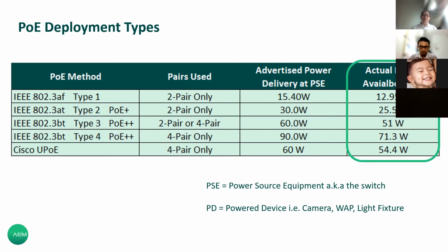So as you can see, we have various voltages specified on the equipment, which we call PSE, power source equipment. Whatever power source equipment you use, be it a switch which provides data and power, like end-span, or a separate power injector, which is classified as a mid-span, it will not provide you the power as in the spec, because there will be losses along the cable.